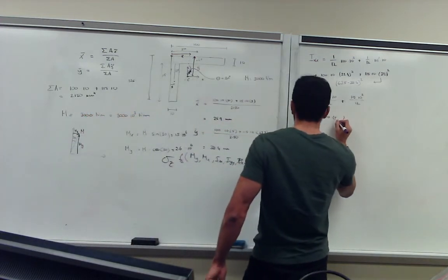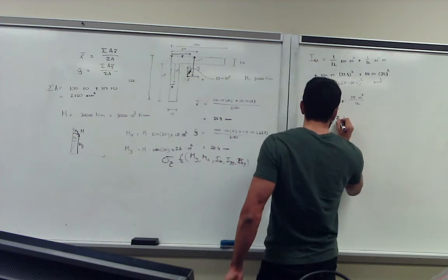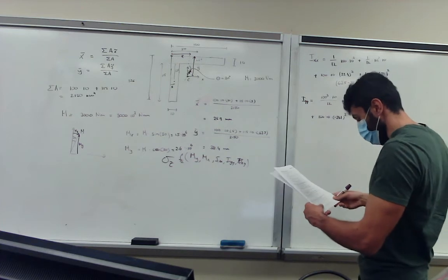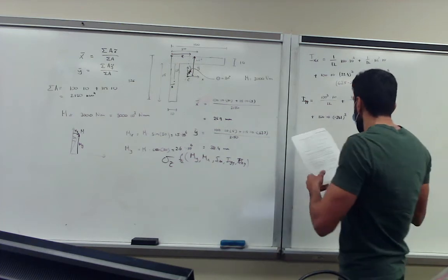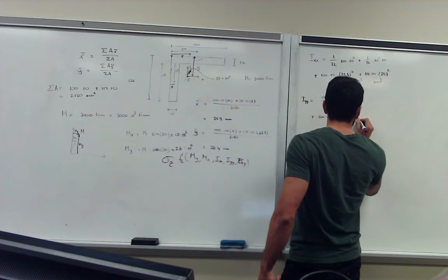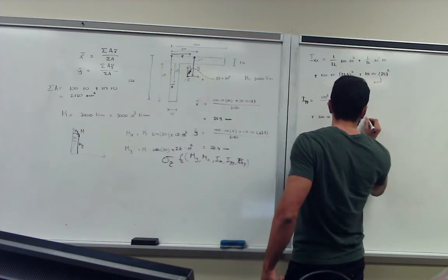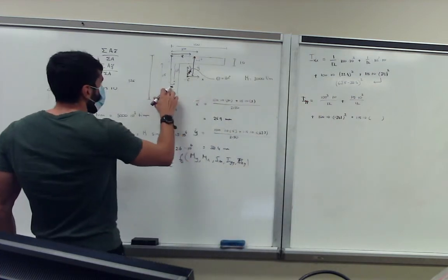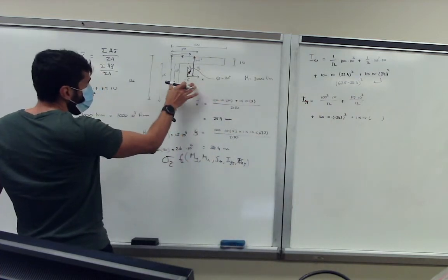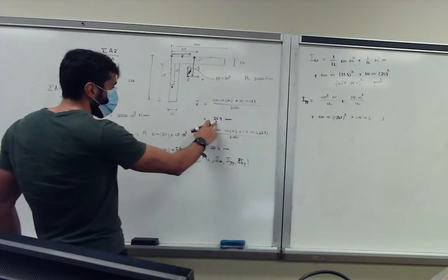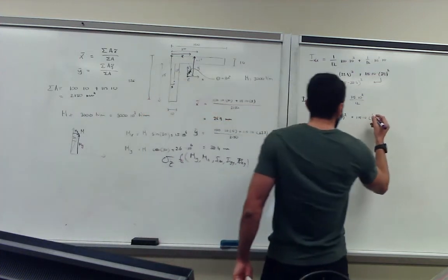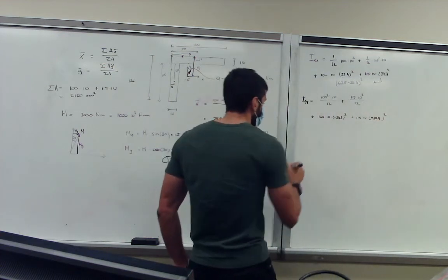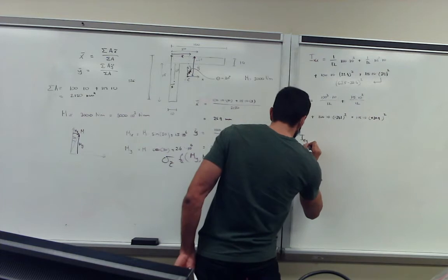So we shift with minus 24.1, but the minus doesn't matter because it's squared, so you can just plug in 24.1, plus 115 times 10, and then again, our centroidal axis is 5, and we shift towards the right. This x dash was 25.9, so we shift with 20.9 squared. And then we get the moment of inertia on xy.